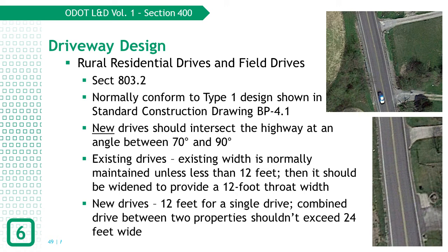Ensure that driveways are wide enough to accommodate a single vehicle turning in or out of it effectively, and the minimum width should be 12 feet. Driveway spacing should be analyzed to determine if there is a safety or operational concern. Combining access or access management strategies may be necessary to maintain acceptable safety performance on the roadway. Information can be found in the State Highway Access Management Manual.